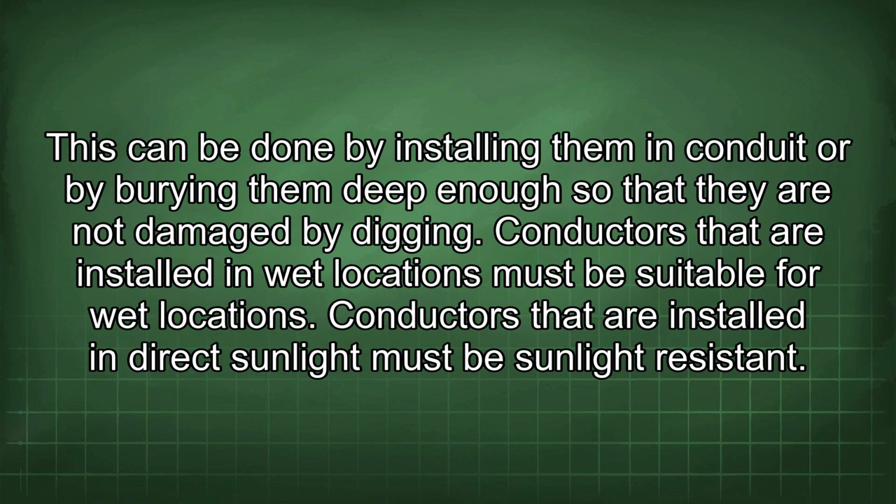This can be done by installing them in conduit or by burying them deep enough so that they are not damaged by digging. Conductors that are installed in wet locations must be suitable for wet locations. Conductors that are installed in direct sunlight must be sunlight resistant.